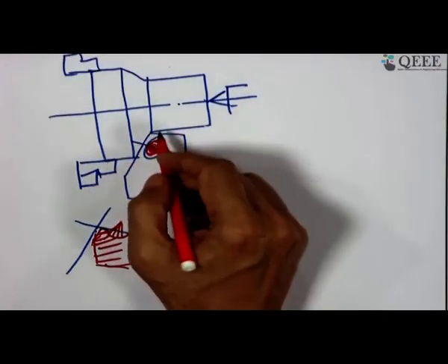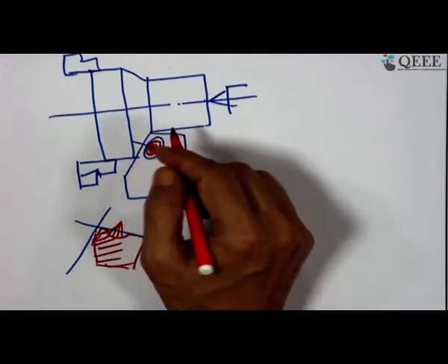However, on the flank side the contact is rigid between the tool and the workpiece, because the workpiece is rigid, but the flank temperature is low. But on the other side, when it is chip-tool contact, it is not that rigid, because the chip is like a cantilever. When it is a flowing chip, it is only held on this side and it is rigid.